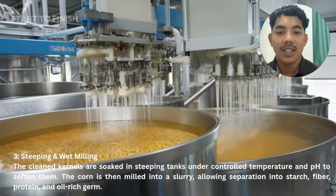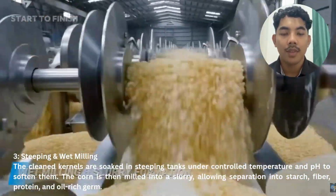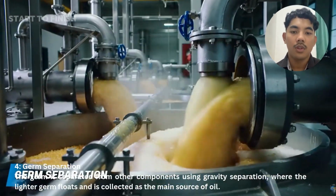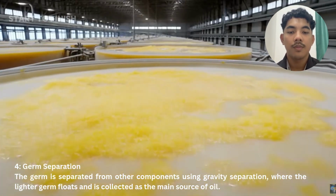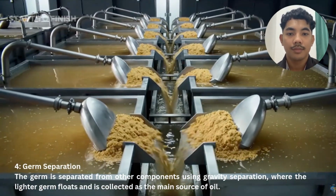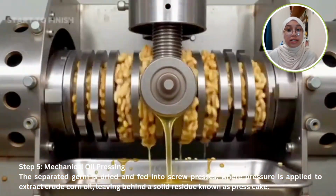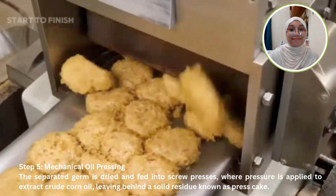Step 3. Steeping and wet milling. The clean kernels are soaked in steeping tanks under controlled temperature and pH to soften them. The corn is then milled into slurry, allowing separation into starch, fiber, protein, and oil-rich germ. Step 4. Germ separation. The germ is separated from other components using gravity separation, where the lighter germ floats and is collected as the main source of oil. Next step, which is mechanical oil pressing. The separated germ is dried and fed into screw presses, where pressure is applied to extract the crude corn oil, leaving behind a solid residue known as press cake.